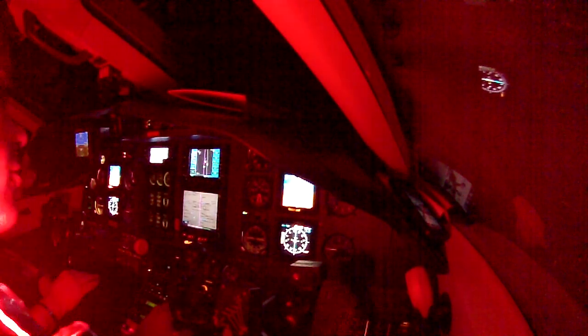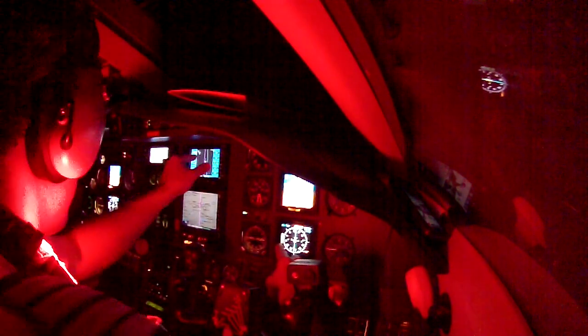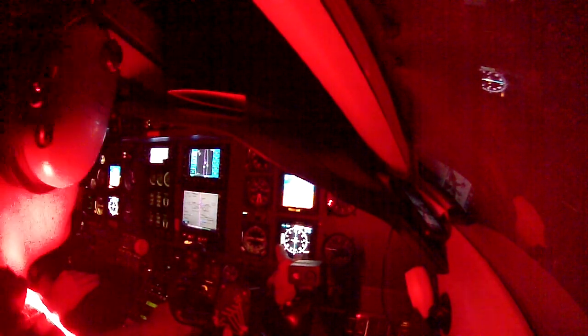Okay? Now back to the HSI here. On the HSI, you have a lot of information. You have GPS information, which is derived from GPS 1, which is the Garmin 530, which is selected here. You have GPS 2, which is the Garmin 430. You can slave it to number 2 if you want. Now we're getting information from GPS 1.